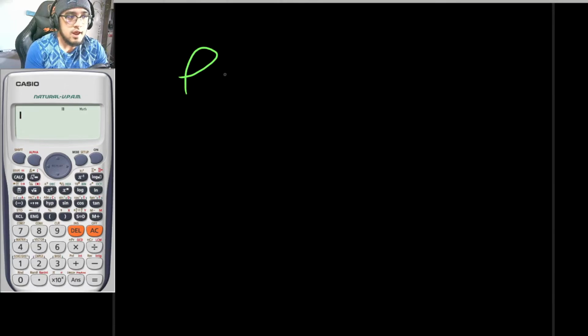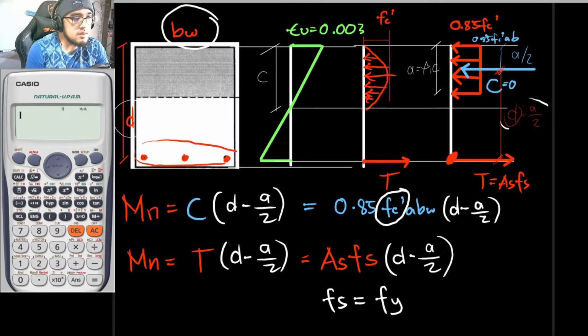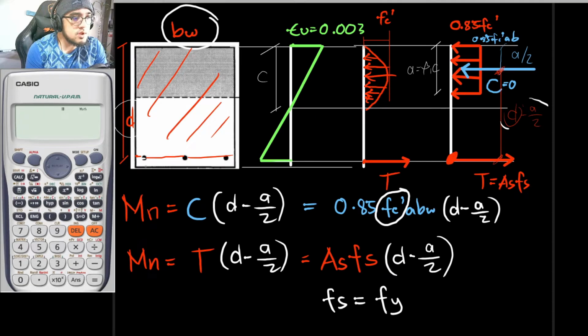And rho in reinforced concrete design is basically the ratio of the steel, your AS, divided by the total area of your concrete up until this point. So by the way, guys, even though there is concrete underneath the steel rebar, we are only considering this part. We wouldn't be considering this area. So we are actually taking this concrete at the bottom part as concrete cover only.